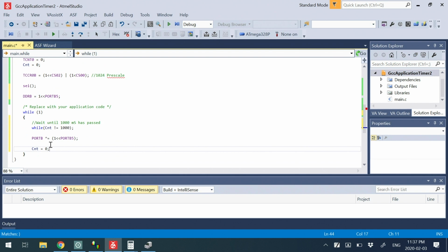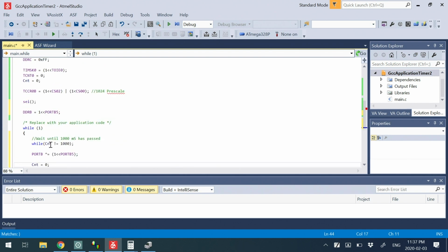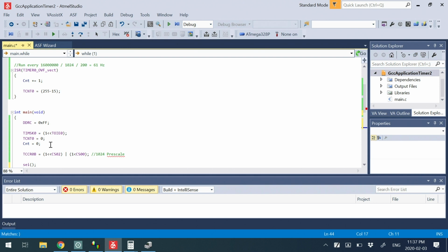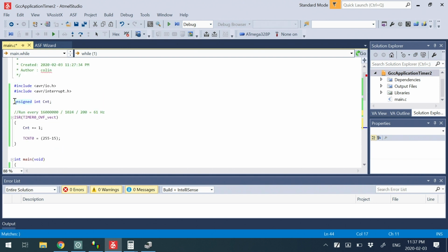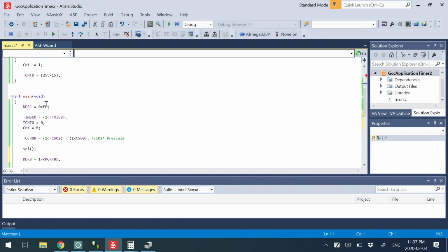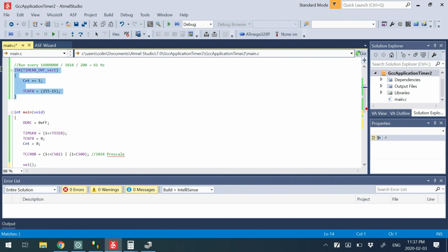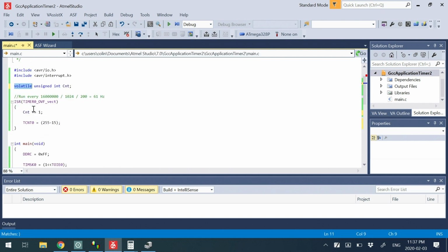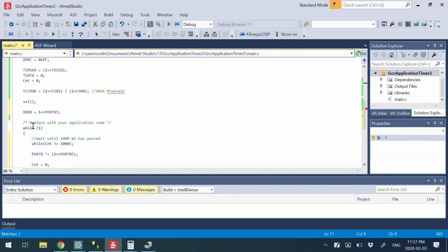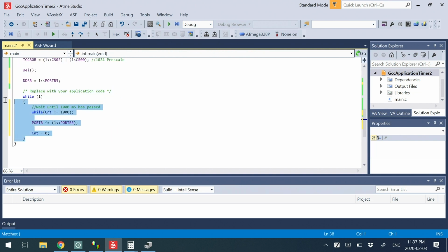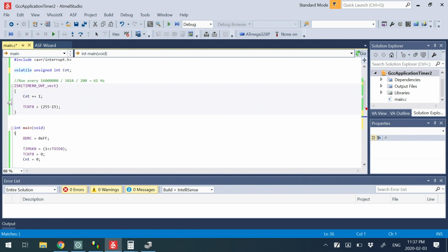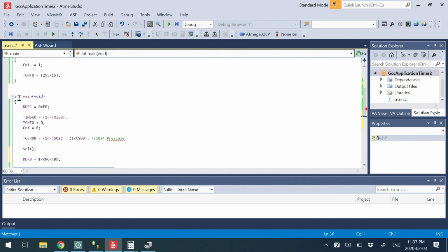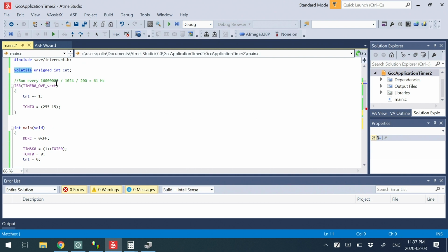So you might think that looks good, but there's a few tricks here. I actually have to do a few little things because of the compiler. The compiler doesn't understand that these interrupts are going to get called. So we have to use this special keyword called volatile. This tells the compiler that the program flow doesn't just exist inside this loop. Every so often, this little magic interrupt service routine gets run. So we set the value as volatile.